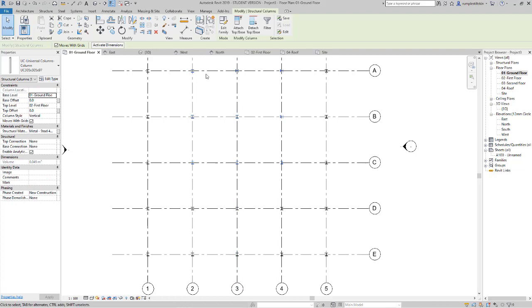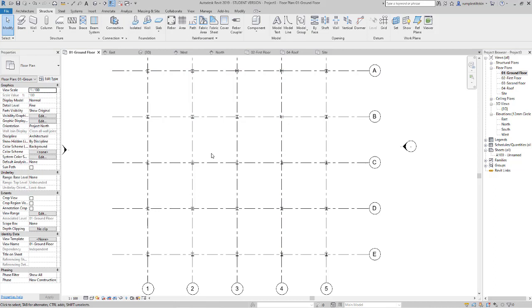So something like that. Now, if I want a core and I want a concrete type of core, because a core is a sort of structural form within a high-rise building. You can hang things off of it. You can usually protect things like stairways, fire escapes, lift shafts within this sort of concrete fire protected zone. So we are going to put in a concrete core onto this. And to do that, we need to change the steel columns into concrete ones.